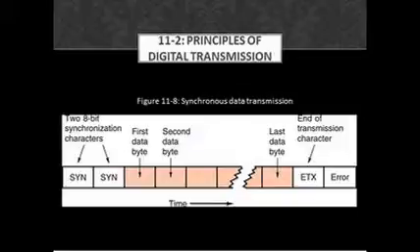At the end of the block, another special ASCII code character, ETX, signals the end of transmission. The receiving equipment looks for the ETX code. Detection of this code is how the receiving circuit recognizes the end of the transmission. An error detection code usually appears at the very end of the transmission.